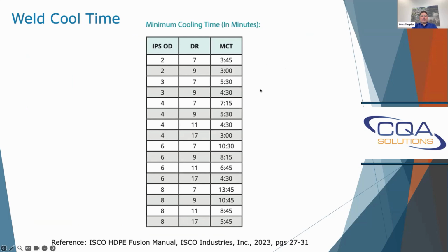And I think that's another consideration for geomembrane installers, that there should potentially be a weld cool down time. I don't know how much it applies to fusion welds. I know you wouldn't want to dump any water on them right after you're done welding them, but I know people sometimes will air test them as soon as the seam is done. And I don't know if there's any issue with that or not. I don't know if there's any studies on it.